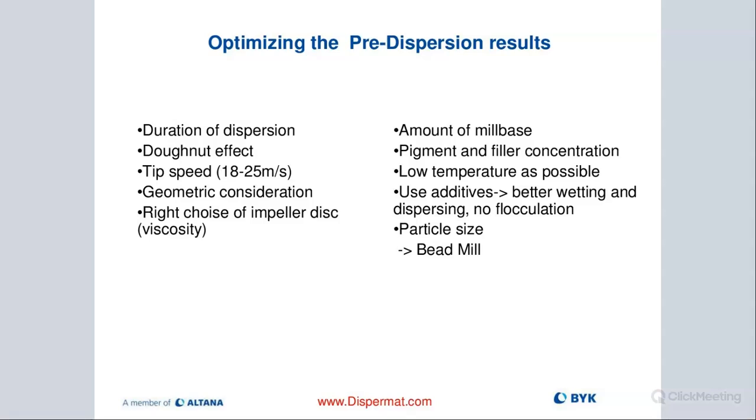And then, of course, there are different types of Cowles blades or impeller discs, so we want to pick the correct one for the type of viscosity we have. A 50% fill ratio is what we recommend. You can go as high as 70% and as low as 40%. But if you're milling with a basket mill, remember the mill head has quite a lot of weight and space. If I'm putting that in the container when I have a 70% fill rate, I have a good chance of pushing my mill base almost to the top of my container, and there is a chance that I might have some spilling. So if I know I'm going to mill with that mill base, I like to stay around 50% fill rate.